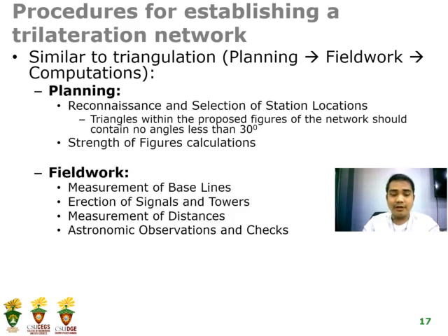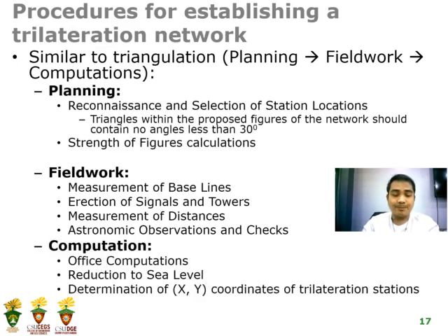And for the field work rather, so it involves the activities of measurement of baselines, erections of signals and towers, measurement of distances, astronomic observations and checks. And for computation, it involves office computations, reduction to sea level, determination of x and y coordinates of trilateration stations.